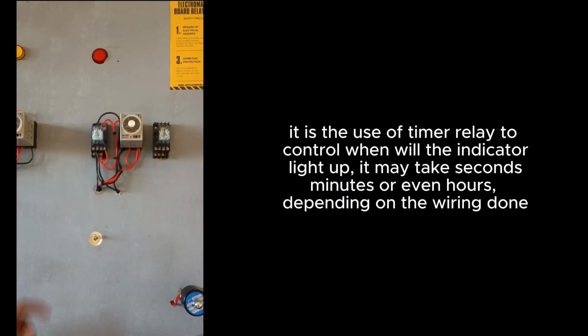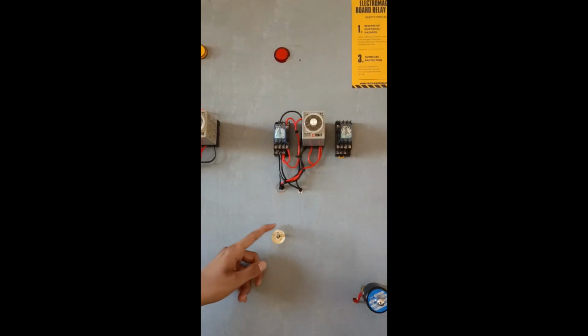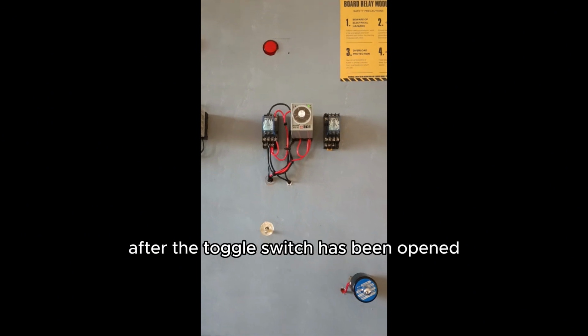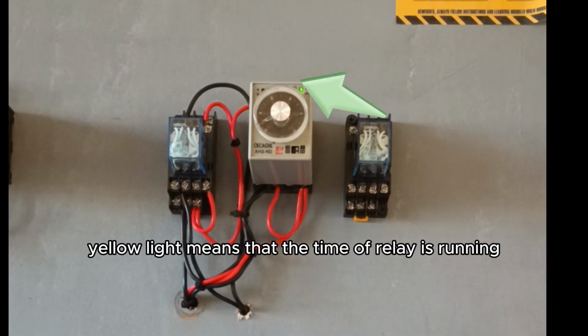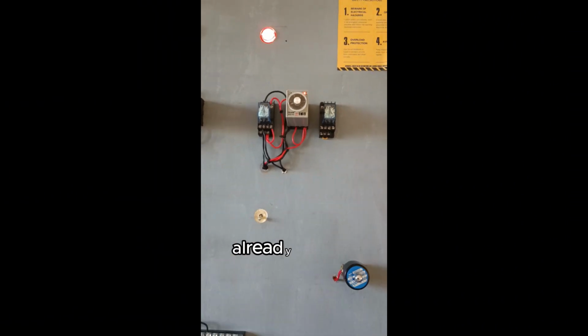Last one is timer control. It is the use of timer relay to control when the indicator will light up. It may take seconds, minutes, or even hours depending on the wiring done. The timer relay will only start counting after the toggle switch has been opened. Yellow light means that the timer relay is running, and red light means that the action has already been done. Thank you for watching.